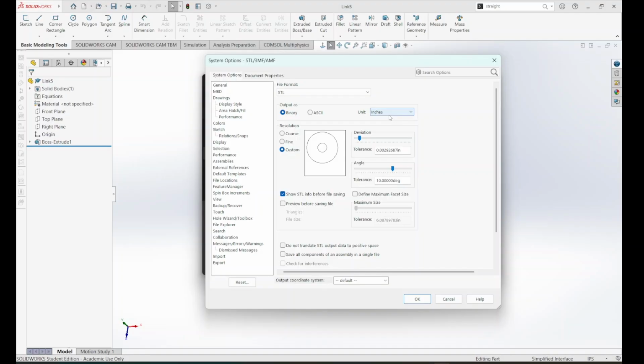So if you're trying to 3D print this, maybe create a 10-inch cube, export it as an STL, try unit inches, and then import it into a slicing software and confirm that it looks like 10 inches rather than 10 millimeters, which I hope should be pretty obvious in some of these slicing softwares, but you never know. If you need help with exporting this, please consult resources like Makerspace, because this is their specialty in getting some of these designs from SolidWorks into STL files, so that way you're able to print them.